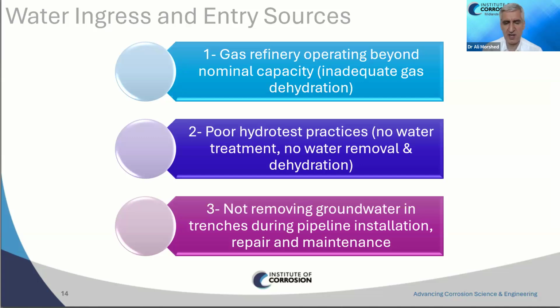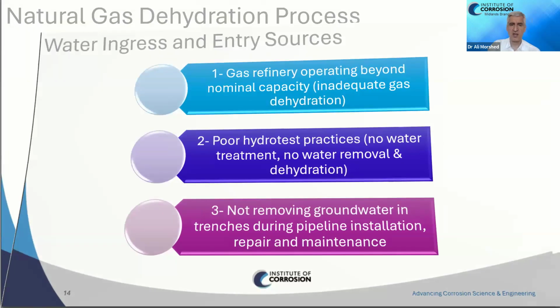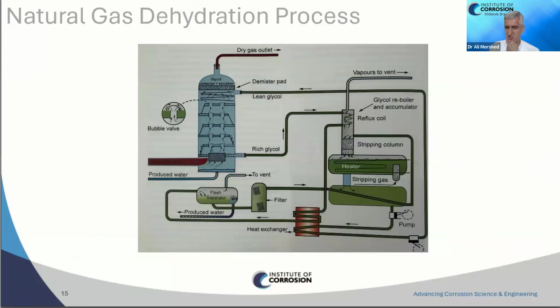If trenches were excavated and there was groundwater in them, the groundwater had to be removed before any installation or before any repair and maintenance practices. But what was happening was that the contractor, with the excuse of not wasting any time, was making the excavations, and if they were filled with groundwater, no groundwater was removed, and installation or repair and maintenance were taking place in these trenches full of groundwater. I've got a few pictures that I will share with you later.